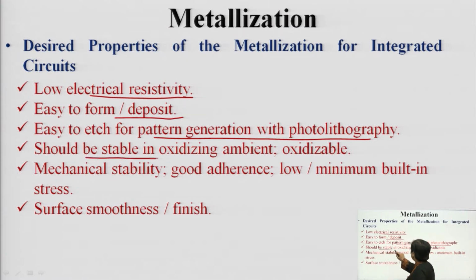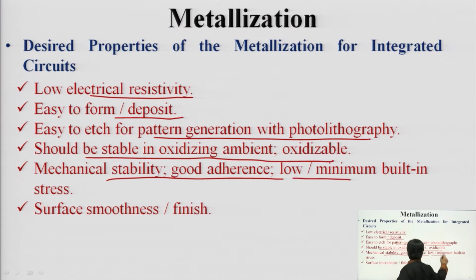Next, it should be stable in the oxidizing ambient. It should not get oxidized easily and should not alter its properties. So, it should be stable. Secondly, it should have good adhesivity property. And lastly, it should have minimum built-in stress.